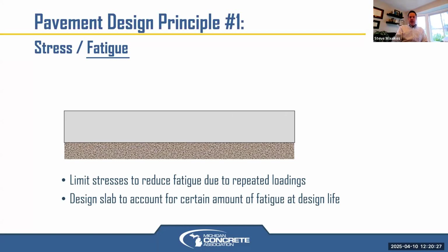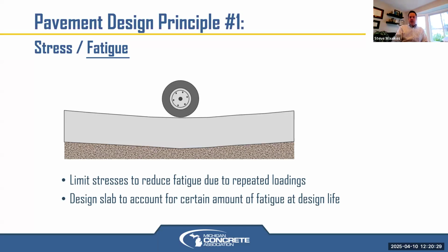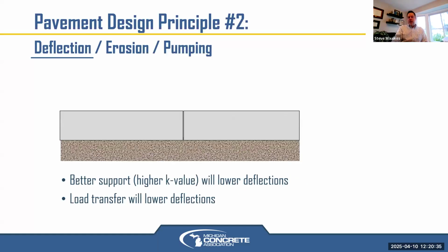Even if we don't exceed the strength, with multiple repeated loads over time we could get that fatigue crack to occur. The other engineering principle we look at is deflection. Again, it's fully supported slabs on grade, so we don't get a lot of deflection like we would with unsupported slabs or slabs simply supported on the ends. But we still account for that deflection in the design procedure.